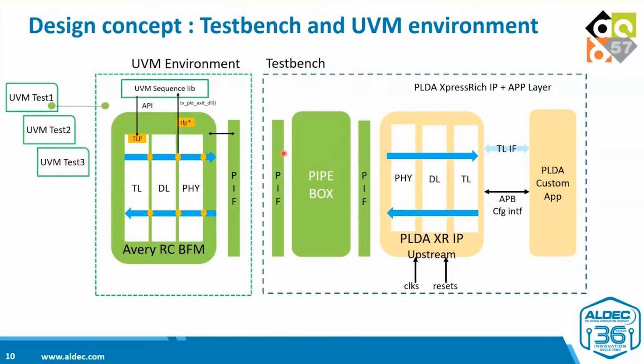And then on the Avery side, we have a root complex BFM. The BFM is a native UVM agent. And so the BFM lives inside the UVM environment. It connects through a pipe interface, which is passed through UVM config.db from the test bench to the UVM environment. And so that completes the integration of the PLDA IP with its own custom app connected through a pipe interface to this pipe-to-pipe connector. And the pipe connector connects on the other side to the Avery BFM, which is living in the UVM environment.